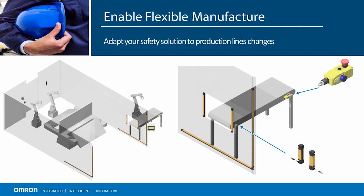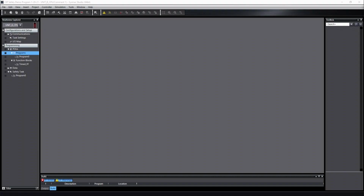I will now demonstrate these features by first showing how to create reusable function blocks of the safety program using Sysmac Studio and show how to easily add additional safety devices to your network by adding a GI-S remote I/O block. Let me show you how easy it is to create a function block of the verified safety program that can be reused for duplicate machines or safety systems.